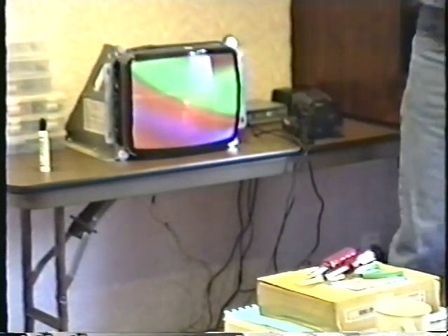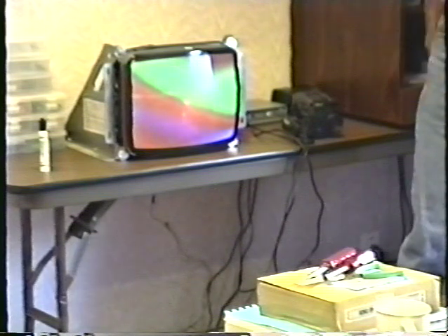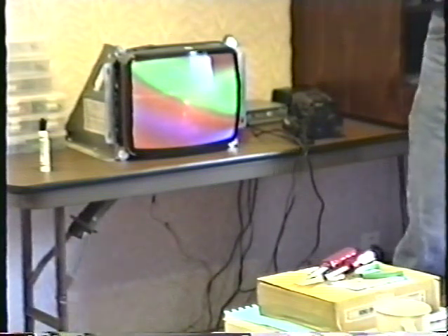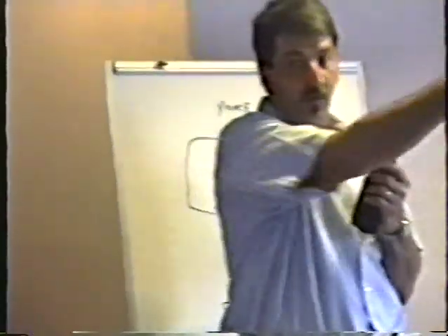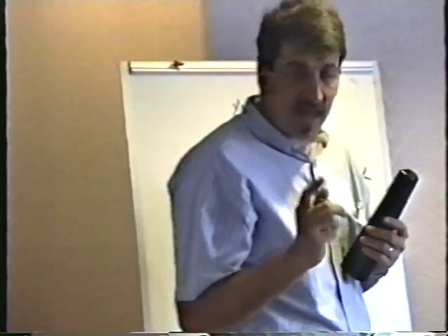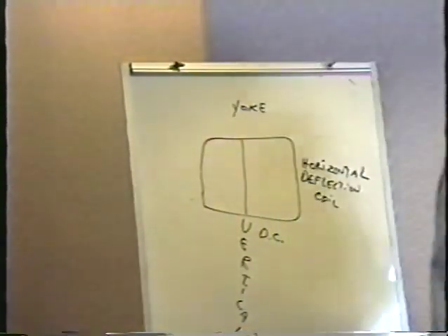I got to one of my locations down by the Mexican border, and all my games look like this. They're all messed up. And magnetism is the thing that did it. Obviously, some kid found that magnetism does that, and he started waving magnets around and screwed up the screen. To prevent that from happening, there is something called a degaussing coil in the monitor.